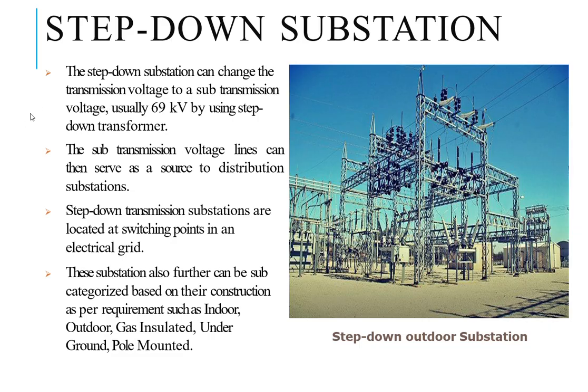Yes, step down substation can change the transmission voltage to a sub transmission voltage, usually 69 kilovolt, by using step down transformer. The substation voltage lines can then serve as the source of distribution substation.